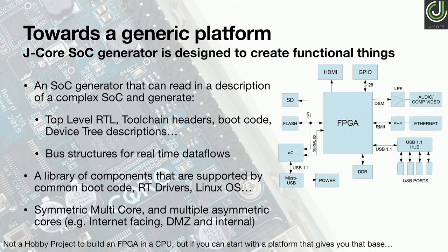Essentially what it is is a very small platform that lets you put your RTL code, your CPU cores, connect sensor interfaces to it with a hat, and run Linux on that, run a real-time OS on that, whatever it is you need to do in order to build your product. And then from there, you inherit from our project or from another project, from maybe a RISC-V project, top-level RTL, tool flows, headers, operating systems. So within a couple of minutes, you can have something running that you can start to do your development on. And I think that that's really very important.